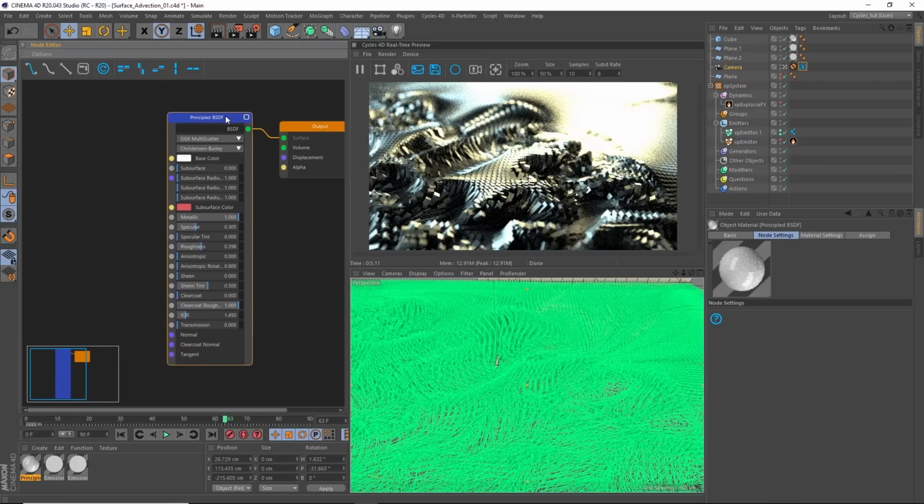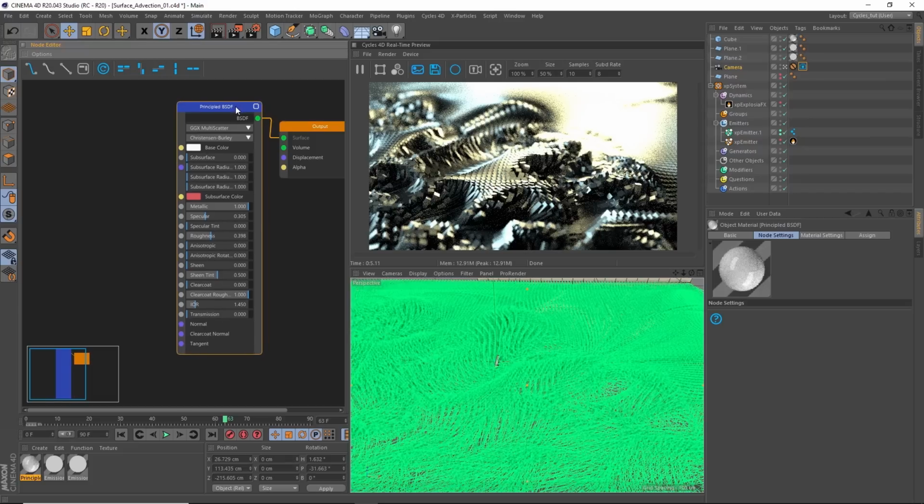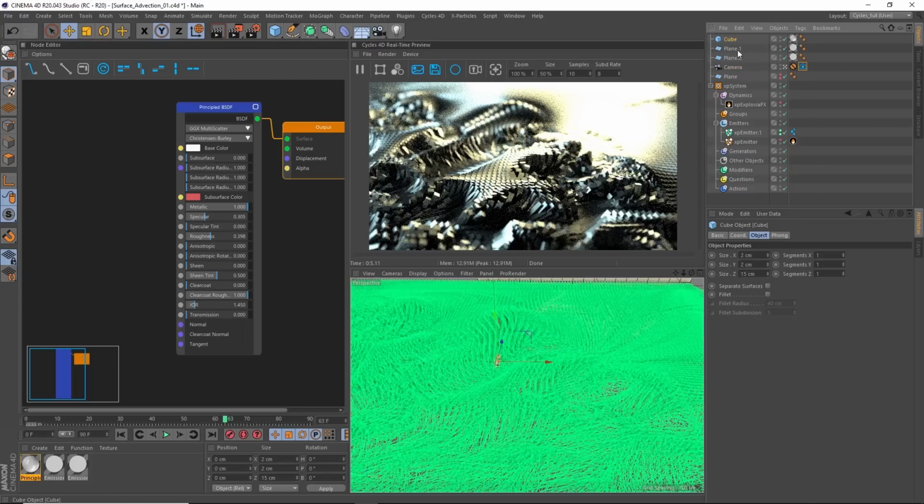So just finally, what we're able to do here, and we mentioned this in another tutorial, if you're using the early access Cycles, we have a new bevel node, which is a rendering bevel node, which means that it does it at render time. So if you want your cubes to have a nice smooth edge, you could do it in the actual geometry that's being instanced by putting this fillet on. But the problem with that is it's actually making more geometry, and then it's instancing that geometry thousands of times, and it's going to chug and slow you down. So what you're able to do with the bevel node is to make that bevel at render time, which is much quicker.